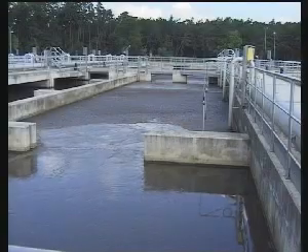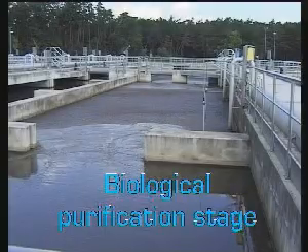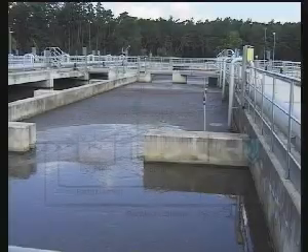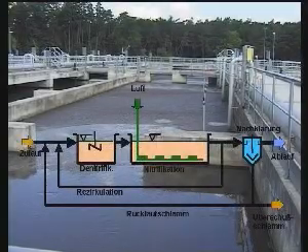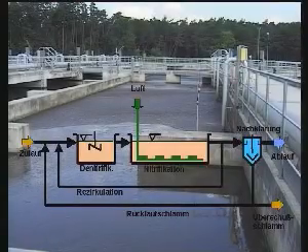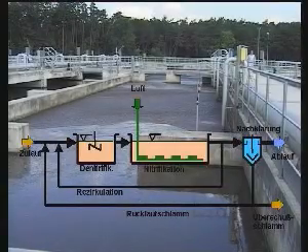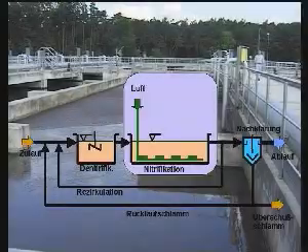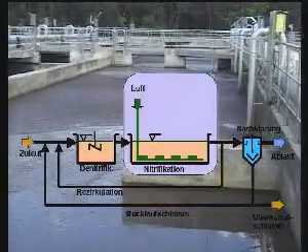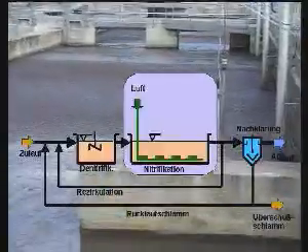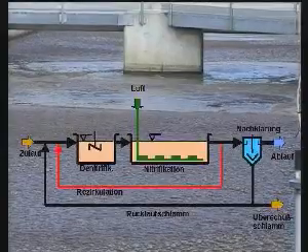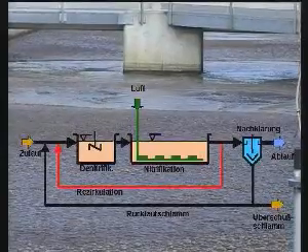After the wastewater has passed the mechanical treatment stage, it enters the biological treatment stage, which at the Langen sewage plant is constructed as a pre-denitrification unit. Here, in addition to breaking down organic compounds, the biological treatment also breaks down nutrients. Nitrification takes place in the aerated zone of the activated sludge tank. In addition to breaking down carbon compounds, this zone also biologically converts the nutrient ammonium into nitrate.